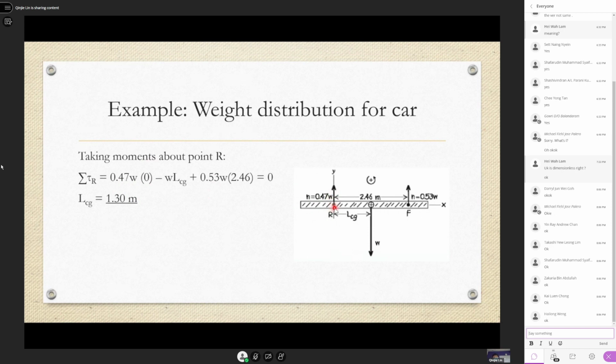So this is a very useful property to use to eliminate unknown forces. Then what other forces do you have? You also have this W, right? So what is the torque caused by that? It is W times the perpendicular distance, that's why W LCG. In this question, we take clockwise as negative, that's why there's a negative sign in front. Then what's the last force?